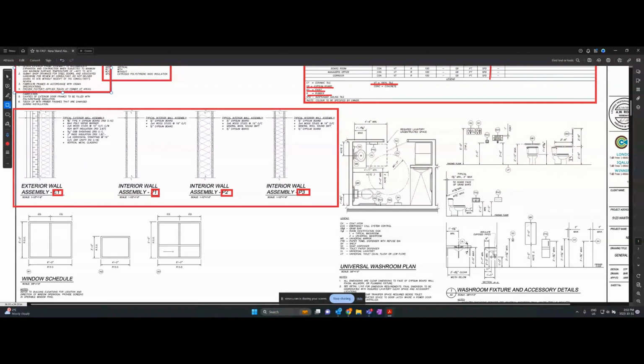And how's the water going to go? Okay, the horizontal strapping is 16" on center. And then we have vertical metal siding. So siding out here, rigid insulation, sheathing, insulation, drywall inside. Okay, we have wall assembly P1.